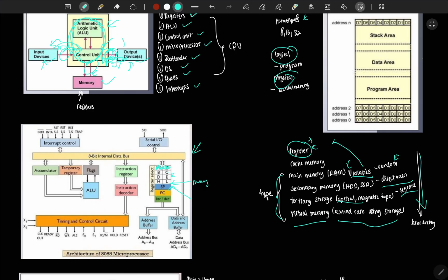And the stack pointer is where we save the memory location. For example, LXI SP, 299H, meaning that in the stack pointer we mention that specific memory address, which will be explained in a while. The program counter shows the next instruction. Maybe now I'm executing 3000H, which may be MOV A, and at 3002 it may be ADD B. When this instruction is running, the program counter shows the next instruction that should be run.